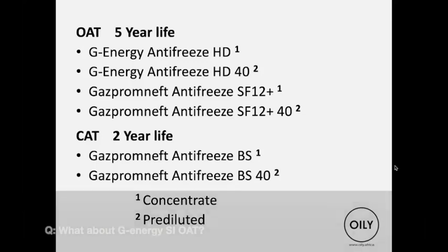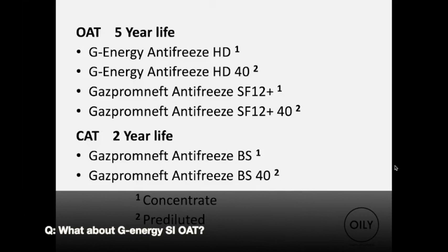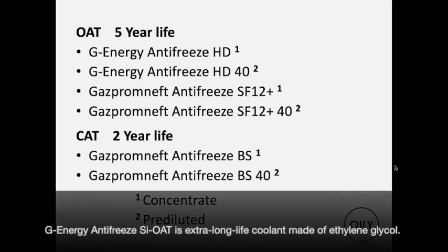Okay, and G-Energy SI OAT. It's an extra long life coolant made out of ethylene glycol. Uses hybrid. Uses OAT. Also free of nitrates, amines, phosphates.